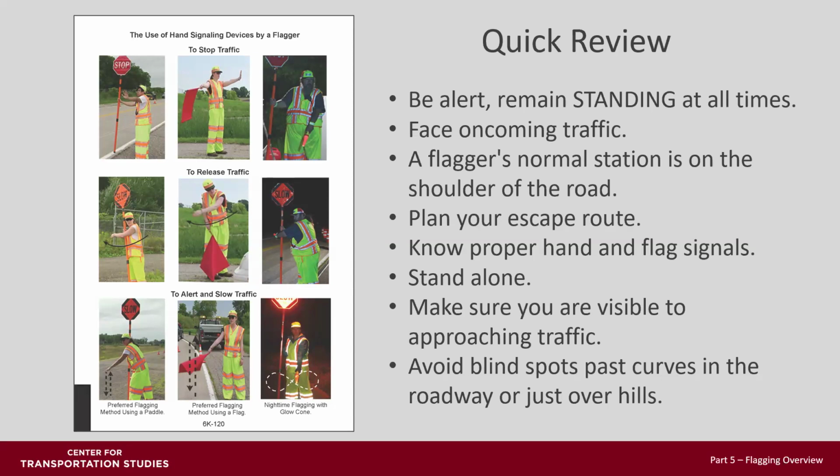Know proper hand and flag signals as shown in the Minnesota Flagging Handbook. Stand alone. Do not mingle with the work crew or motorists. Make sure you are visible to approaching traffic. Consider not standing where the sun is impeding visibility or standing in the shadows. Review the decision sight distance chart in the Flagging Handbook. Emergency vehicles have priority rights. Allow them to pass as safely and quickly as possible.